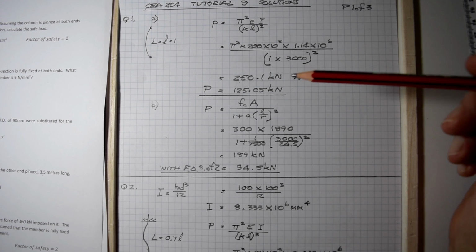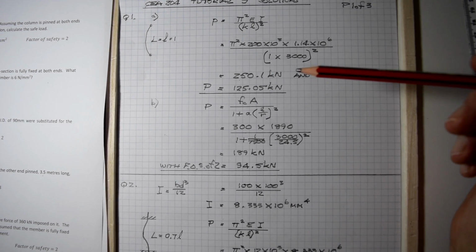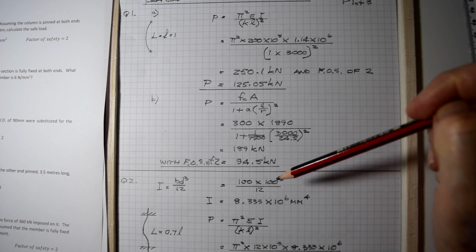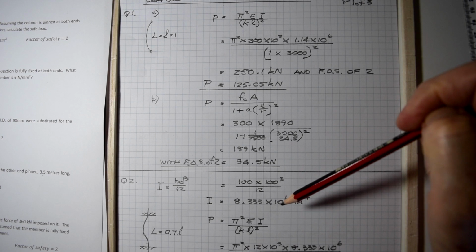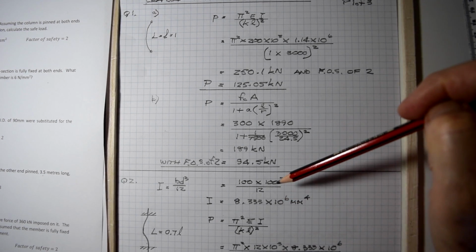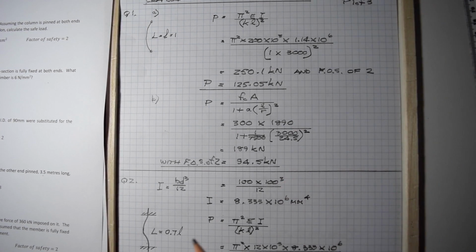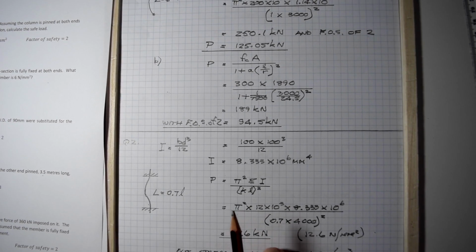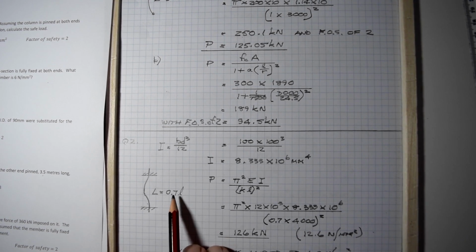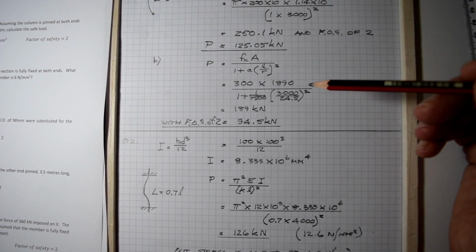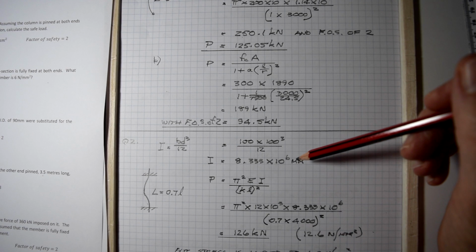Now, question number 2 is a timber post, 100 millimeters by 100 millimeters in cross-section, and it is 4 meters long. It's fully fixed at both ends. Over here we can see that, fully fixed at both ends, so the reduction factor for the length is 0.7 from the table, 0.7 times the length. So using Euler then,